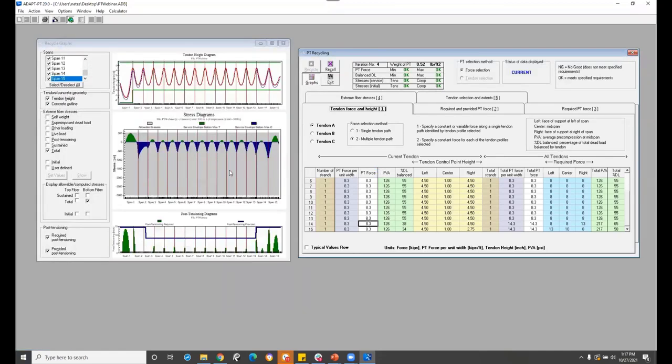And there we go. Now we can see a little bit better that we have some tension stresses in the bottom of our spans. This is much closer to what we are expecting, or it's much more optimized, right? We're utilizing this capacity that we have. We are able to have some tension stress here. And you can even see over on this far end that our pre-compression is a lot more reasonable. There is this one area that the pre-compression is high, but it's not every single span. So we're using a lot less PT in this case.